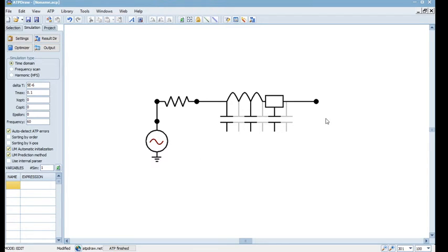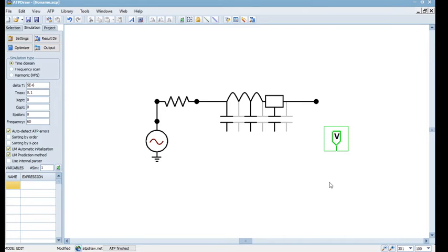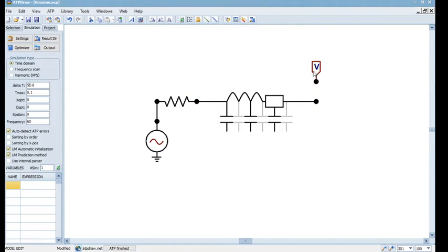Yeah, and here it's open circuit, so always you can place a resistor if you want very high, or since it's a model, much better in this context right now, so we'll just keep it open circuit. Fine. So we'll just place a voltage probe, and just before setting we'll set it to single phase, and ensure it's single phase. You can just place it over here. Fine. And we want to measure the input also, so I'll just copy this and paste, and I'll measure it here. So the input, I'm saying exact input voltage, or in fact this will be the measurement for the voltage applied to this RL, the complete circuit.